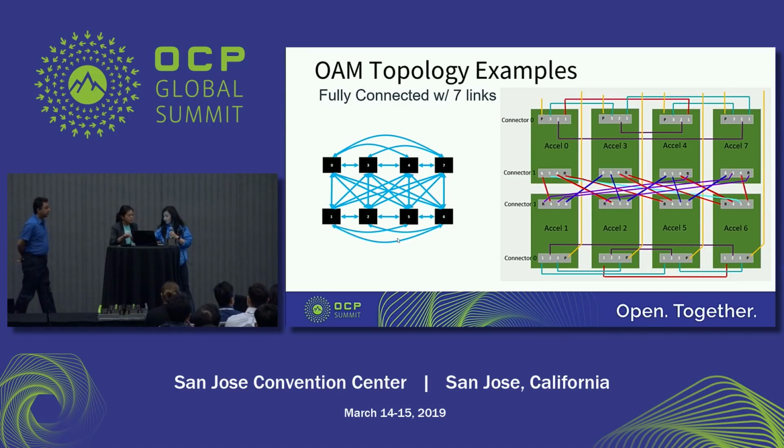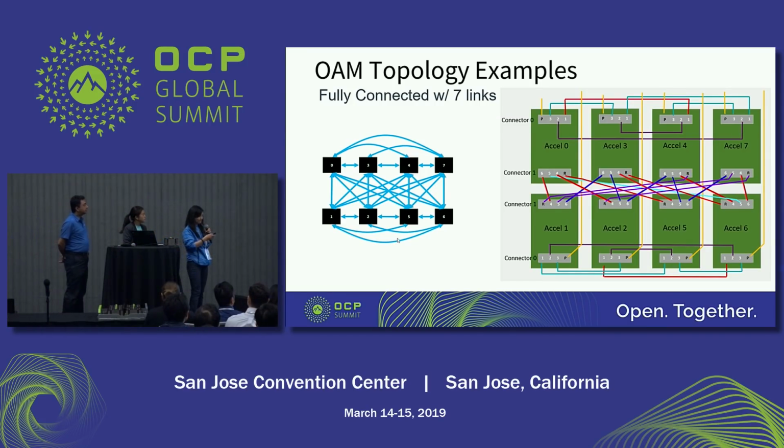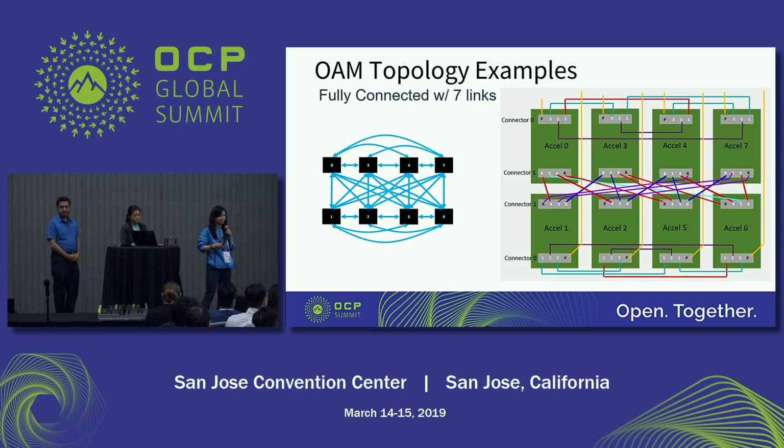Coming back, okay, yeah. So the right side is really the layout mapping. Each of the ports, how they map to each other, and then we consider trace lengths to balance that design.